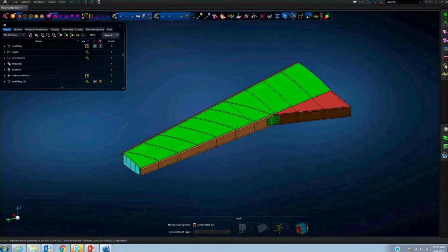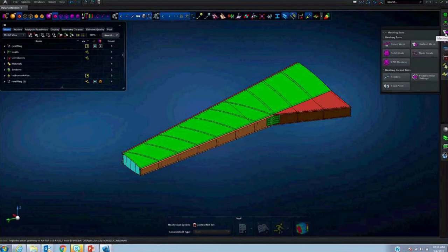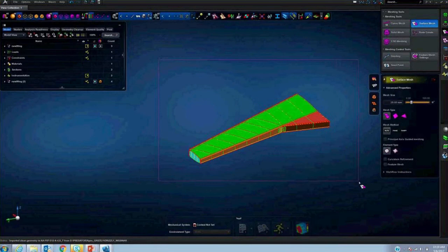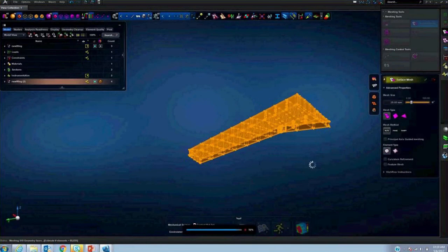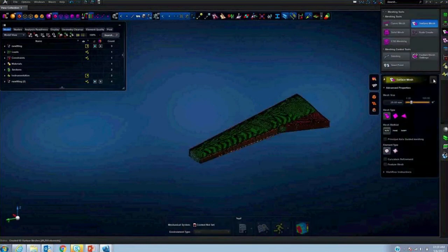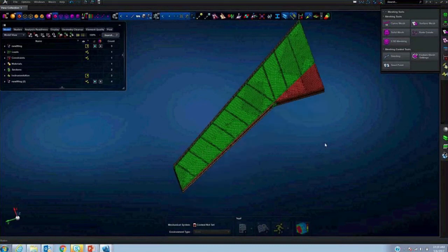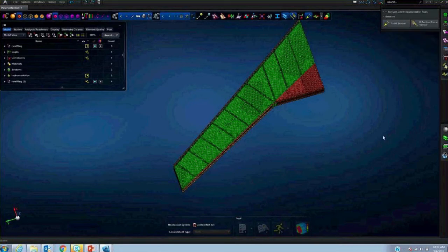Right. Here in model, let's see how elegantly we can create a cross-section, then take a look at the cross-section forces. I'm going to quickly mesh this model, maybe 25 millimeter element size. And once the mesh is done, it's not that you need to create the mesh before you can cut the plane. You can cut the plane even on the geometry, and then you can mesh it, and we take advantage of the generative behavior. Let's see how we can cut the cross-sections.